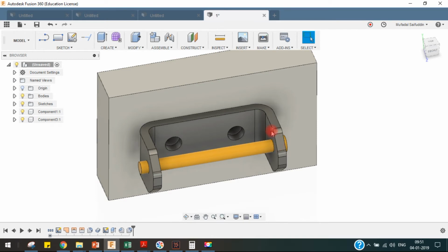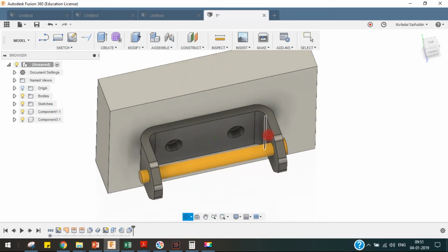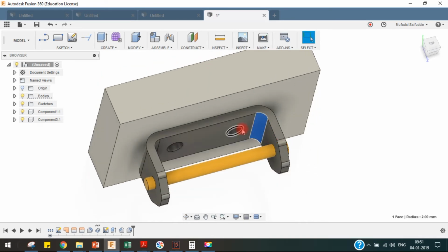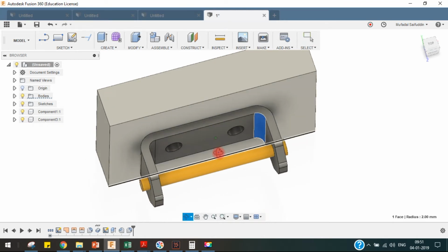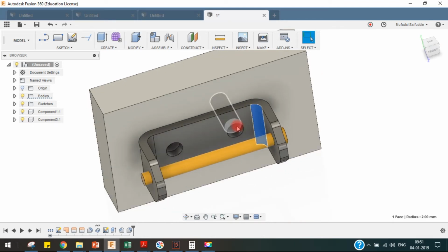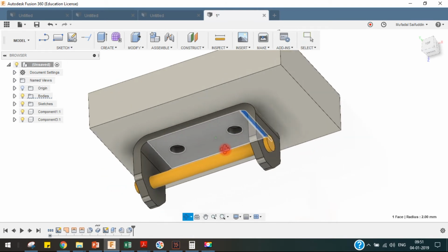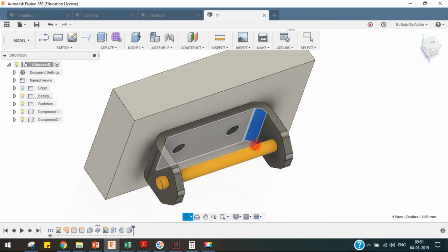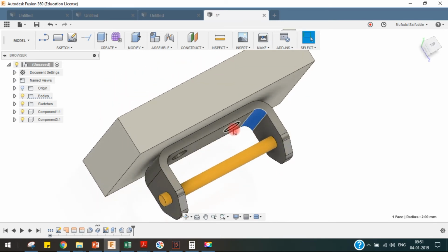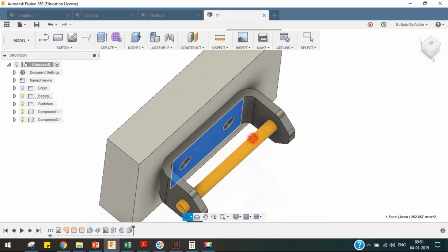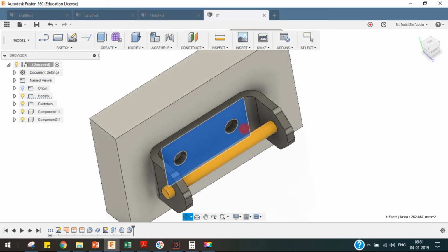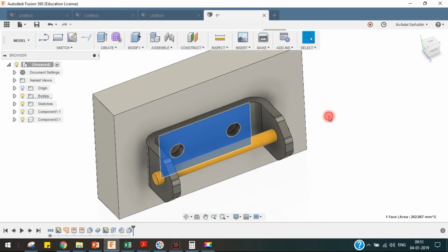Over here we made one consideration, that is we made sure that the clearance between the fillet and the hole is maintained more than 2. And also we maintain the clearance between the hole and these edges to be more than 2 times the thickness. Apart from that, we have given enough distance from the mounting edge to the pin such that the bolt can be assembled or the nut can be assembled. So this is the design of a simple bracket.